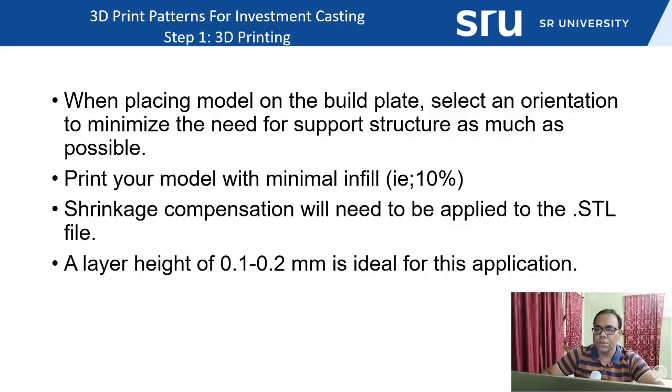I will be discussing the different steps required for manufacturing an investment casting mold design using the additive manufacturing process. So first, in the first step, you have to start with the CAD design model. When you are placing the model on the build plate, you have to orient the part so that it minimizes the support structure as much as possible.